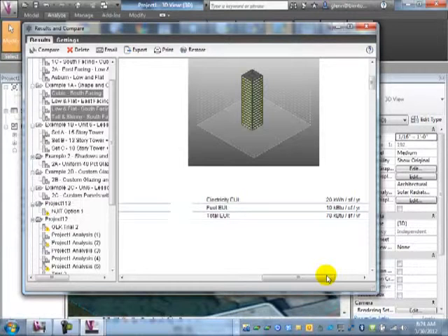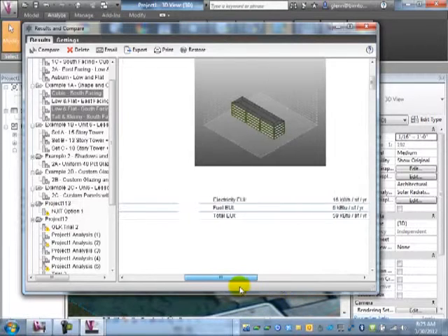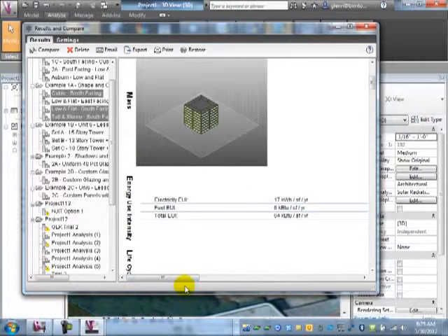Now, intuitively, think about the amount of surface area exposed to the elements for that building versus the other ones. It has a lot of exposed surface for the same amount of volume encompassed, so it does very poorly. It's exposed to the wind, the cold, and the heat an awful lot. If you think about the math, cubic buildings, or even spherical ones, would do better in the scheme of things because you're encompassing a lot of volume with the minimum amount of surface area. So these types of buildings tend to do a little bit better.